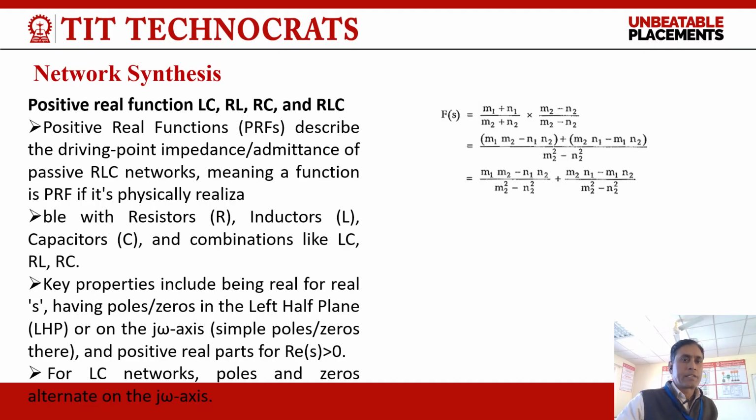So the question arises, what is network synthesis? A positive real function, that is PRF, describes the driving point impedance and admittance of positive RLC network, meaning a function is a positive real function if it's physically realizable with resistor, inductor, capacitor and combinations of these like LC, RL and RC. The key properties include being real, having poles or zeros in the left half plane or on the j omega axis,